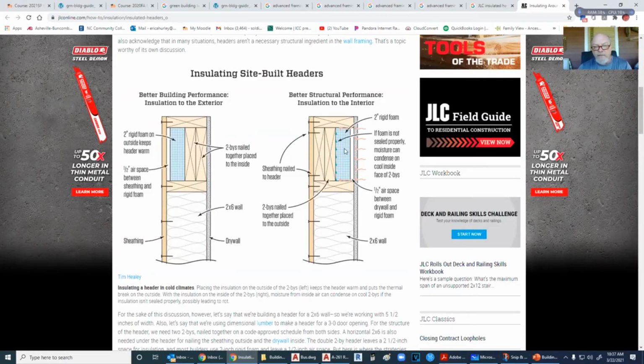If we put the insulation on the inside, then maybe we catch some water in here, because this has a very, very low perm rating. Anytime you have a surface touching a surface and water condenses in there, it stays. Remember that, we talked about the ink quill pen, I think it was maybe in here.